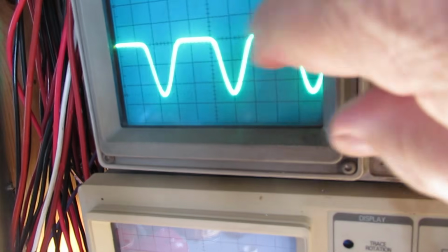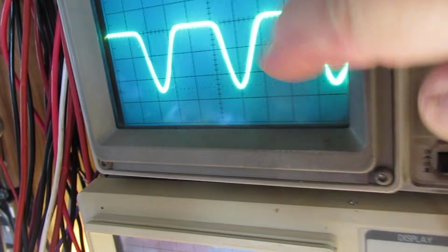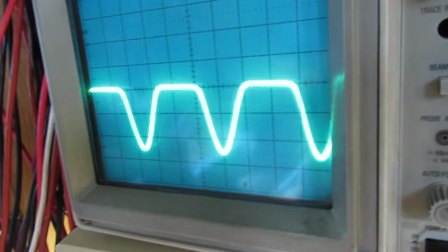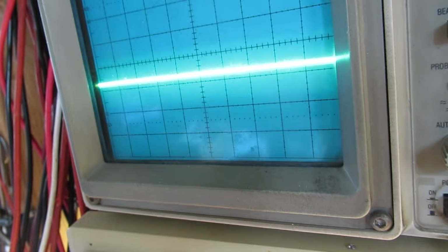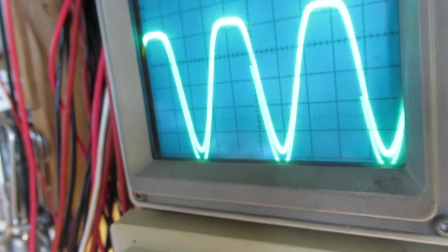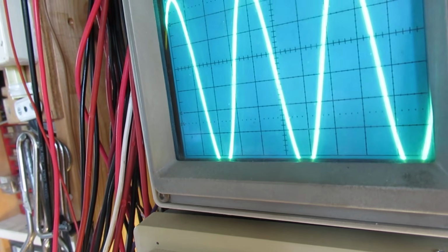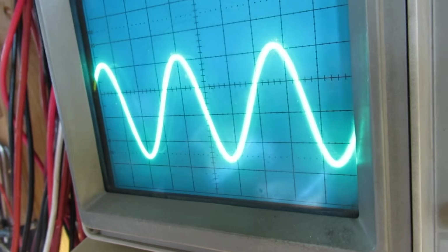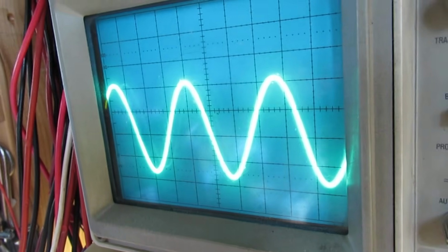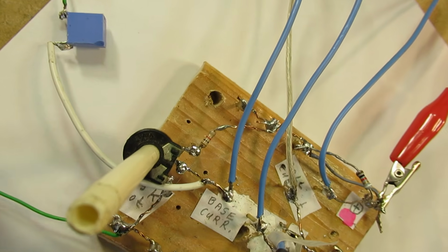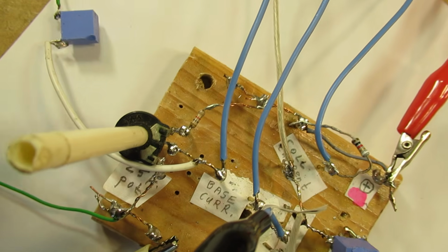But this doesn't have to be a problem when you want to use that transistor for another purpose, not amplifying pure sine waves. So bring the bias completely to zero. Of course the transistor cannot function. And here I turn the bias pot. So you can see that there is always an ideal bias, and that is directly related to the voltage where such a transistor works at its best, and that's visible here. And there's also that direct relation to the value of the potentiometer, of course. It's also related to the base voltage.